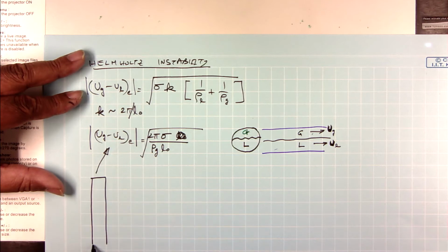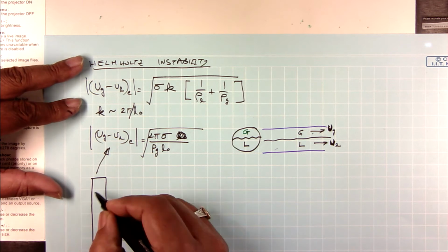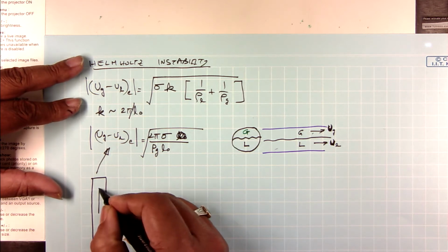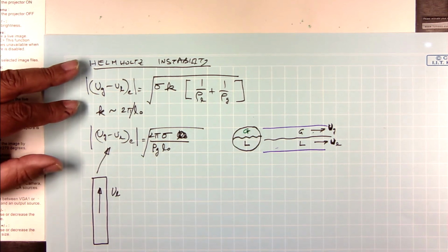All right, so let's therefore go into a vertical flow configuration, and the simplest way to do it is what is known as adiabatic two-phase flow, which is if you don't have any heat transfer. So let's look at the adiabatic two-phase flow first. In adiabatic two-phase flow, there was another video I wanted to show you, that how you introduce the gas phase into the liquid pool also makes a big difference. So let's say I have a pipe that's going in the vertical direction, and I have a uniform flow of liquid, UL, in the pipe, fully developed flow.